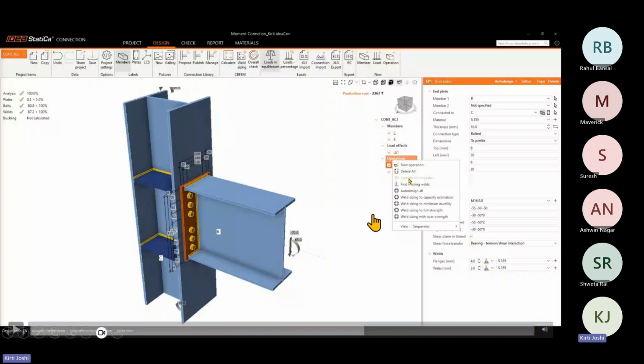You can check this in your code setup tab. When the stop at limit strength setting is enabled, the software automatically stops the calculation when any part of your connection exceeds its allowable strain. For example, you might get a message that the analysis reached 70% or 60%, which represents the maximum load the connection can carry before failure.